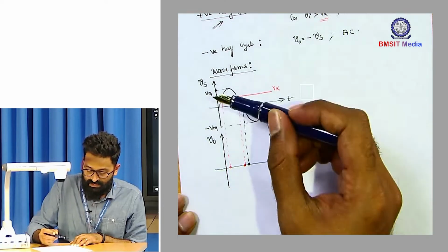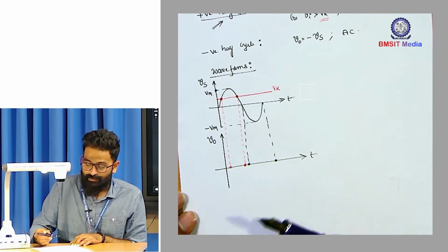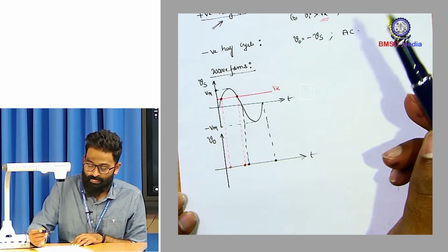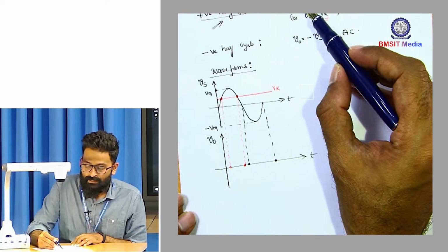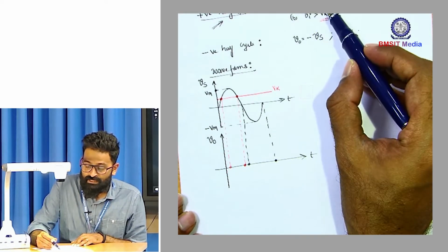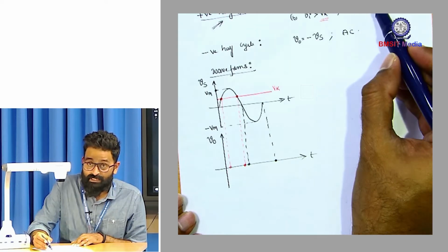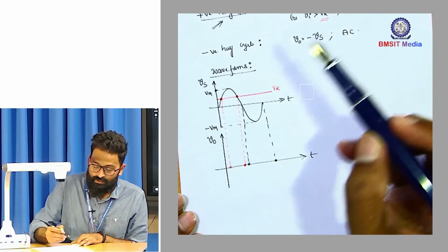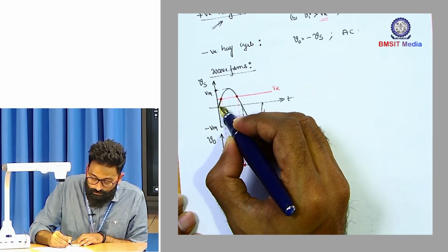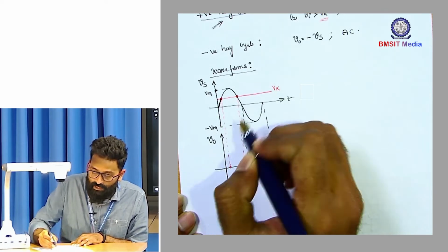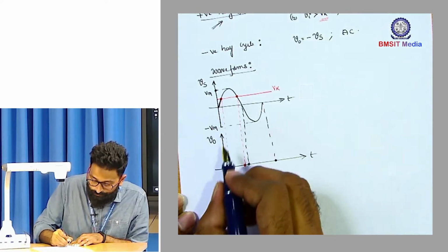These transition points will help you in sketching the waveform. So what you have seen in the analysis is, as long as input is less than the threshold voltage, output is equal to input, right? So for the values of the input less than Vk, output is input.